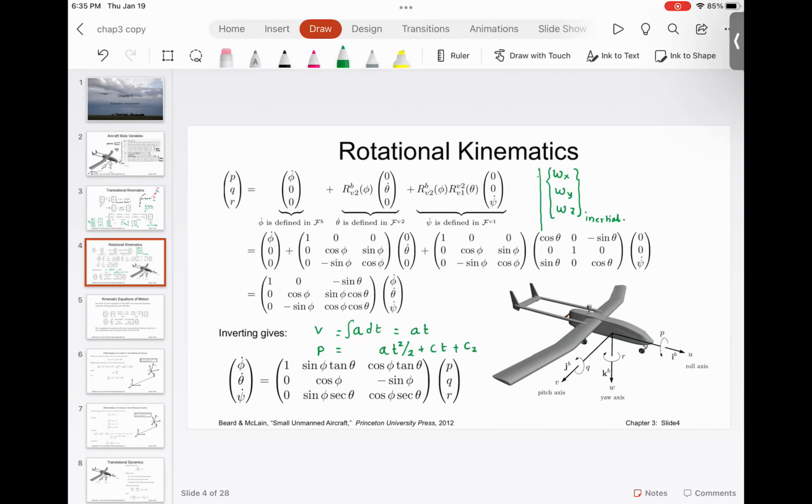Now imagine if this acceleration is not accurate. So acceleration is not a flat line. Instead, this acceleration is kind of changing and going up and down, up and down, up and down. These teeny tiny changes, that error, will get multiplied by t square by 2, and t is continuously increasing, which means that initially, even though your error may be very small, as time goes on, the integration of error is going to be very, very large.